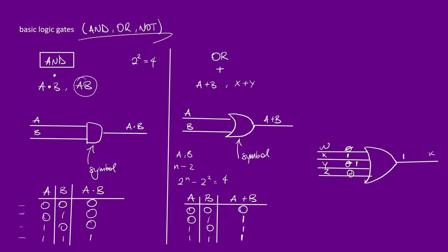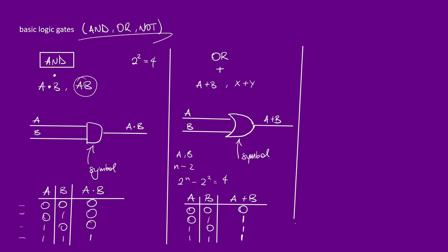If all of them become high, then my output will stay high since I have at least one input that is high. So that's the trick with working with the OR gates, okay? You're able to get a high output if any single one of your inputs comes on. You've got the AND gate, you've got the OR gate.